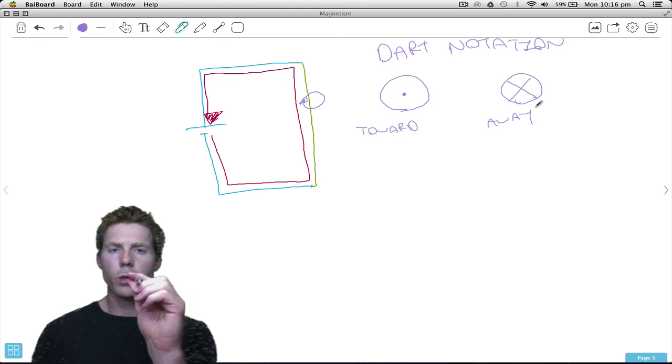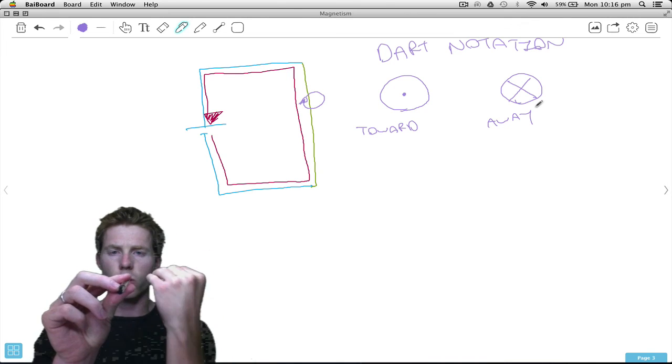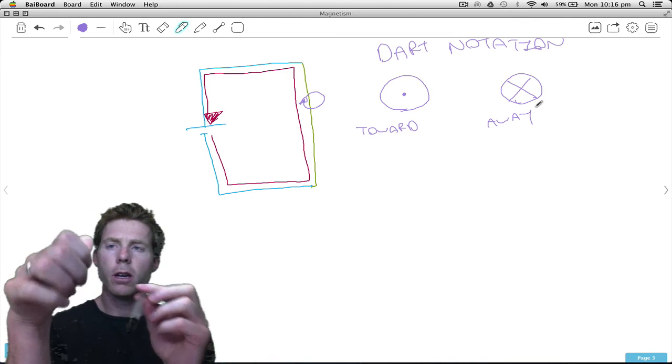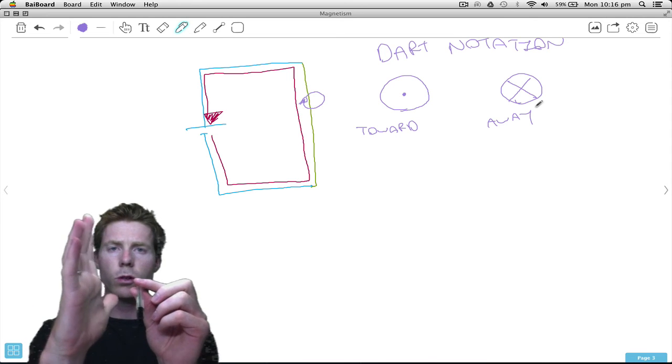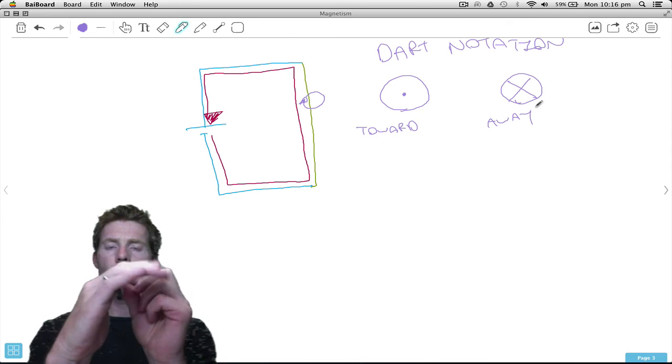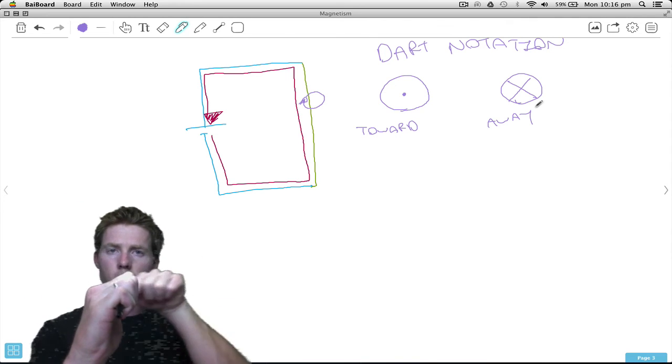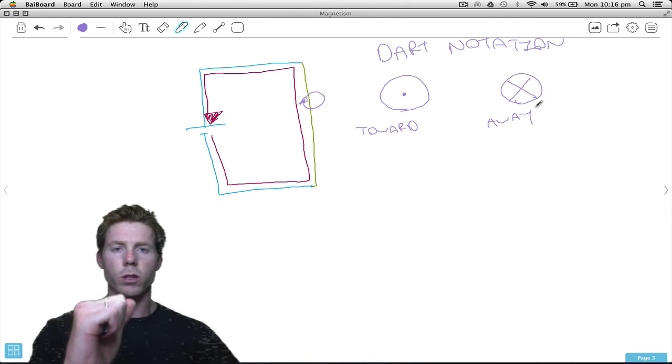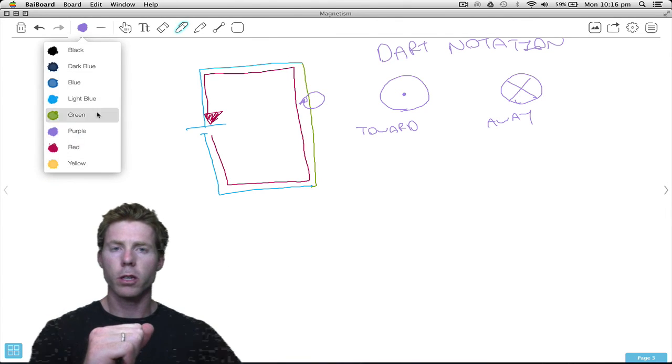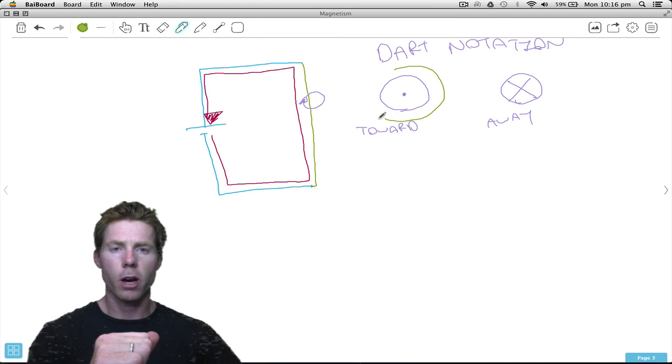So the first one I'll do is toward. So the electrons are traveling towards me. I get my left hand, my thumb pointing in the direction of those electrons, so it's coming towards me. I wrap my hand around, and this is the direction of the magnetic field that is built up. So it's actually going to be going this way around the wire.